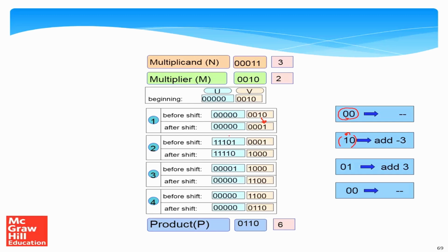Why? Because you just add plus 3 to it, and you'll clearly see that the result becomes 0. And so this is what minus 3 is. So basically we can also see for a 4-bit, minus 3 will be 1101, and we are just extending its sign, right? So this is minus 3.